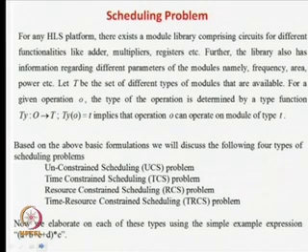Let us now see that there are different types of scheduling problems. We will see them one by one. One is called the unconstrained scheduling problem. Actually we should not call it unconstrained, because there is only one constraint: data dependency has to be managed. Otherwise, there is no constraint like completing all the operations in four time steps, no requirement of so many adders or subtractors, no resource constraint, no timing constraint, etc. This is called unconstrained scheduling, but of course, you have to follow the dependency.